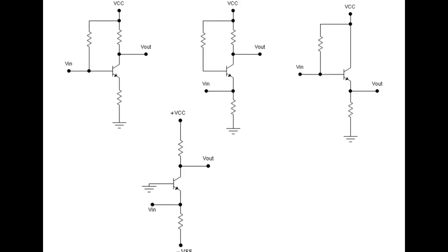So these are different examples of, this is emitter bias. And we got all types of options here. And it works on exactly the same principle. So if this guy drops 1 volt, let's say this guy right here drops 0.5 volts. Now, this 3 volts and this 0.5 volts is set by this collector current. This voltage right here is going to be the difference, right? You understand? So let's say I have this set at 0.7 of a volt, and this right here is setting at, what was this, 6 volts? This is setting at 5.3 volts.